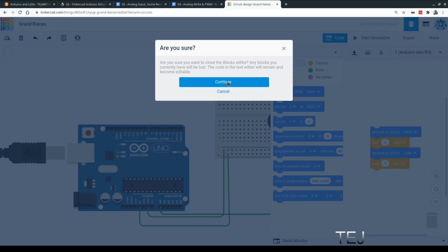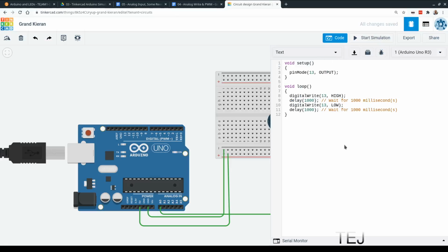We're going to use text, so you click on code and go to text. Our pin for A0 will be done a bit differently. We don't need to set up the pin if we're using analog. I'm also going to take the opportunity here to show you how to use serial output. We're going to erase everything inside of our setup and loop, and we want to set up our serial bus so that we can see output in the serial monitor.